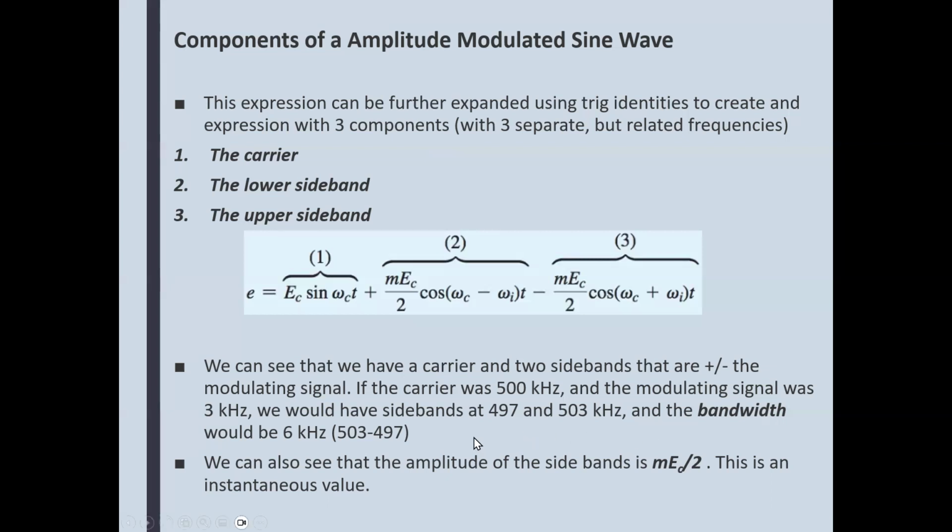On the FFT, this is what we would see if we had a sine wave, say 1 kilohertz. But my voice, for example, consists of many frequencies and their harmonics, and music as well. So you're not going to see a spike on the left and right sides. You're going to see a dispersed, almost rectangular shape. You're going to see some hairy mess on the left of the carrier, and some hairy mess looking thing at the right side of the carrier.